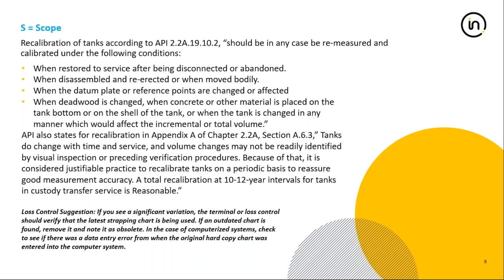Also, the API recommends a particular frequency where you should do it. What they recommend is a 10 to 12 year interval for a full recalibration of the tank when the tank is operational and there is no other situation that might affect calibration. You should redo it every 10 to 12 years. And I just want to let you guys know that in Colombia, for example, our customers have actually changed this recommendation to a 5-year cycle.